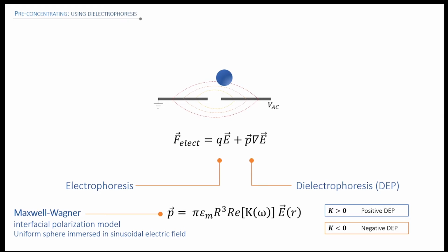So we need new strategies to enable rare event and needle in a haystack kind of detection experiments. In our research, we overcome this limitation by incorporating a dielectrophoretic trap into the single molecule sensor for selective confinement of the analyte molecule from ultra-low concentrations.